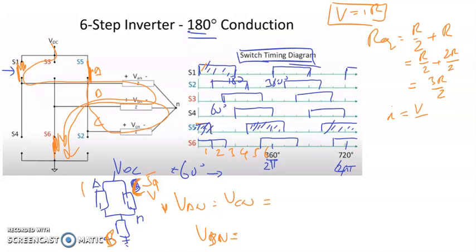For I, we divide the source voltage Vs by the equivalent resistance, 3R over 2. The 2R shifts to the top, so we have 2 over 3 times Vs over R. This is the value of I that flows from the source to the ground.